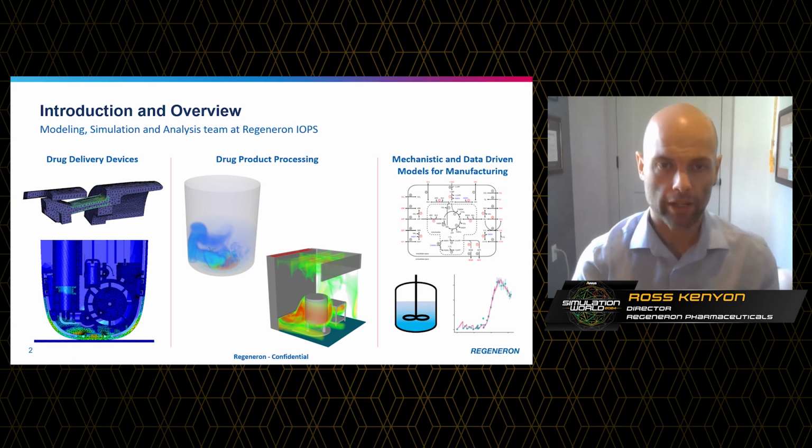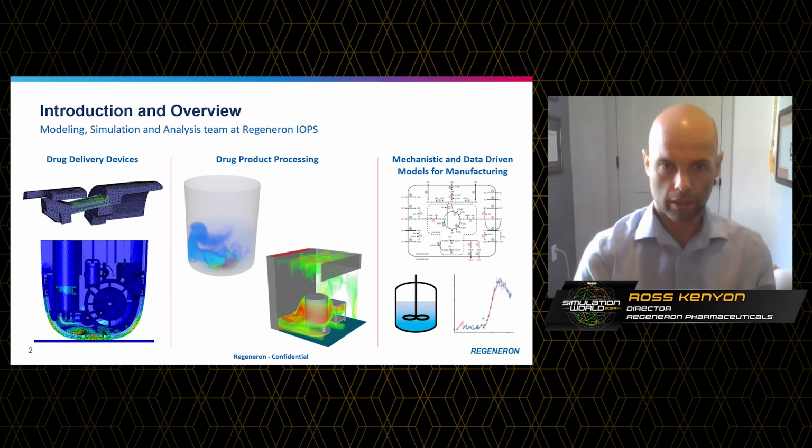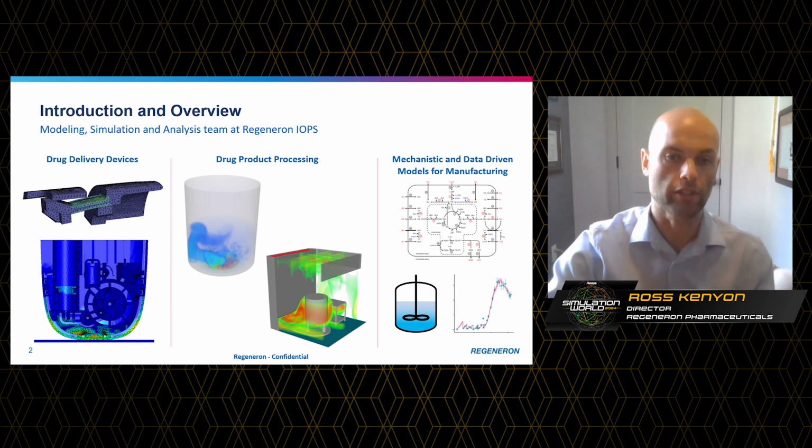My team has three main areas of focus. The first is on drug delivery devices, and what we're doing here is working in partnership with the product design teams as they develop novel devices for our injectable drugs. A lot of the work here is split up into system modeling, so mathematically modeling the operation of the devices, and then the detailed models of the mechanical performance. These span the simple linear static analysis to nonlinear materials behavior like hyperelastics and creep to high-speed dynamics like drop testing.